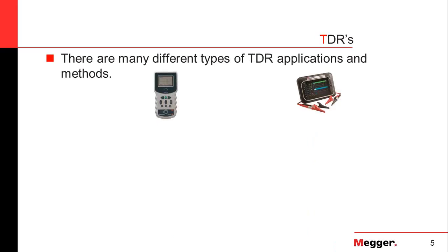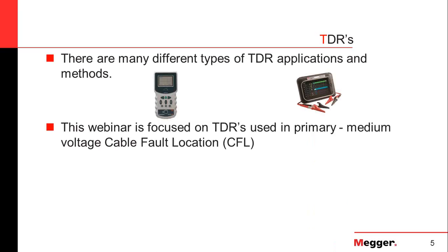TDRs, time domain reflectometers, there are a lot of different types of TDRs and different applications and methods. This webinar is going to focus on a specific type and application, basically using a TDR on a primary medium voltage cable, specifically cable fault location.